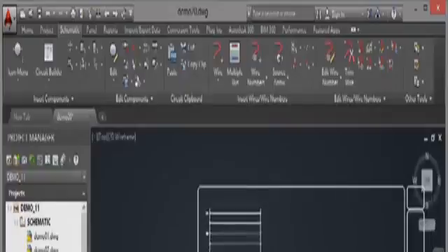I've still got a reference start of 900, still got an index of 1, but can you see I've got a redo tick there kicking in? What that means is, because I've changed some of the elements in the fields here, like rung spacing and rung count, it'll redo this particular ladder. So when I click on OK, you'll see when I zoom out now, it's got a different number of rungs, and the spacing has all gone a little bit screwy. Can you see that? The reason being is it hasn't actually physically updated the ladder. What it's done is it's updated the spacings down here. All I've done is update the spacings. So what I would need to do here is add some rungs to the ladder itself.